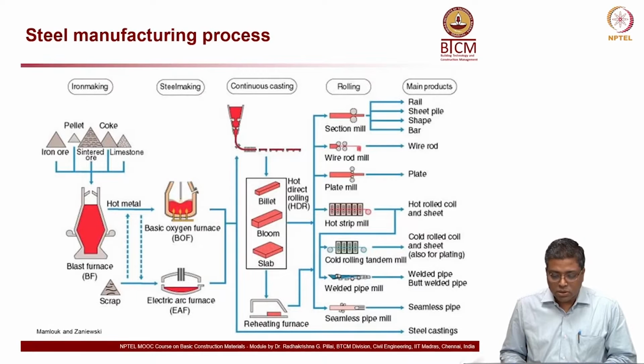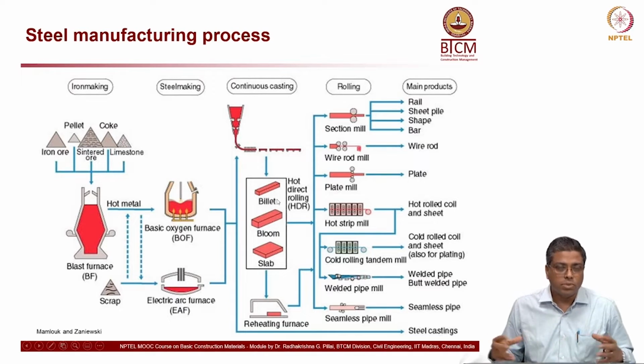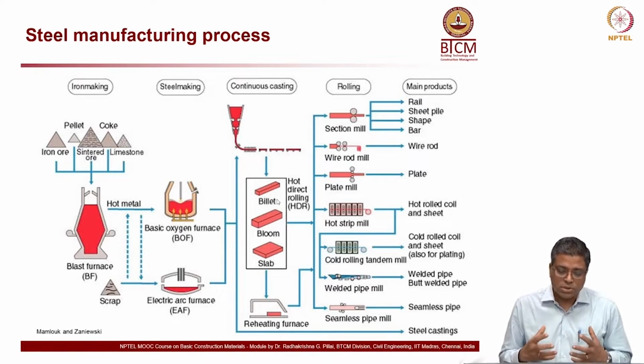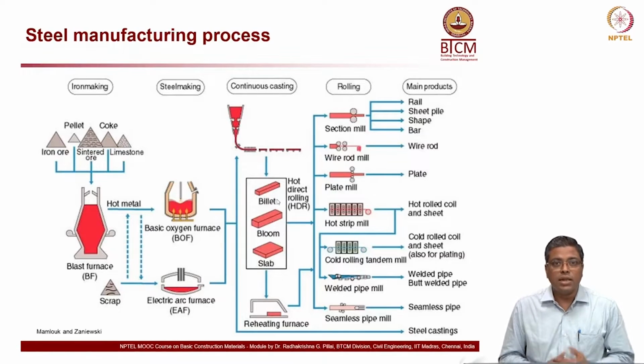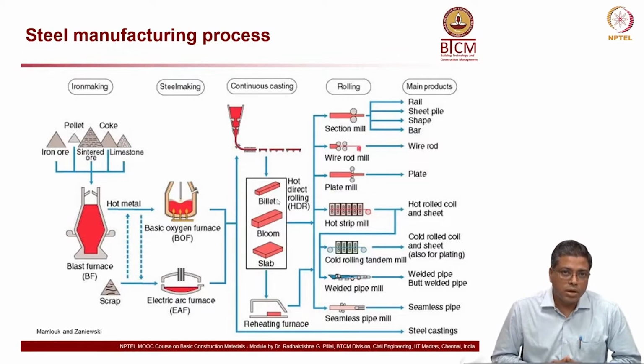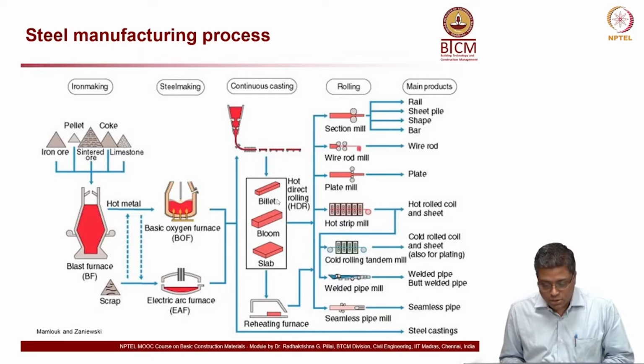So this is just a quick look at the manufacturing process. Essentially, the rebars are made from billets. Billets are prism-shaped elements which are produced first, and then they are put into some kind of roll to make different steel sections, including the rebars. Okay, different types of dies are used for that.